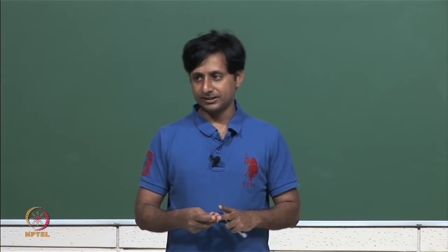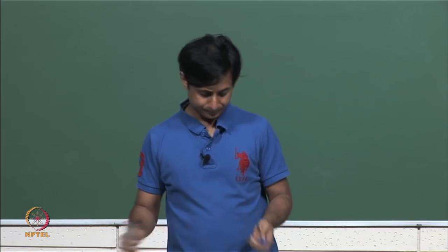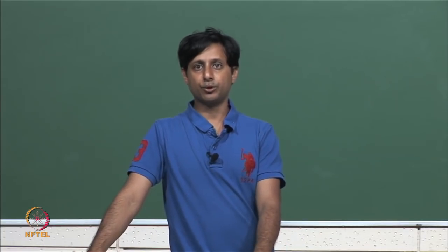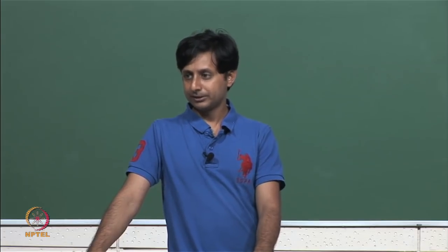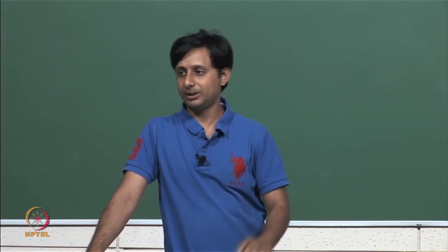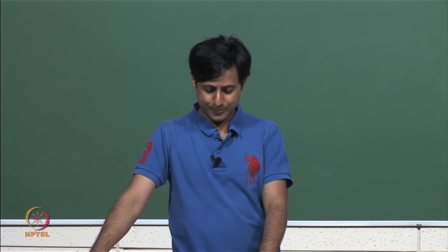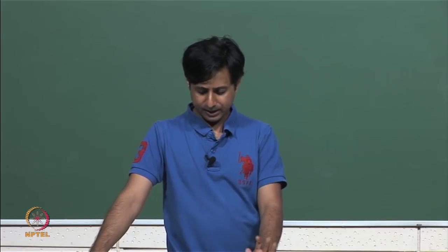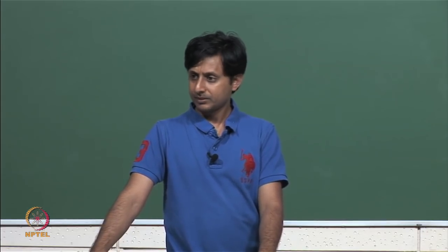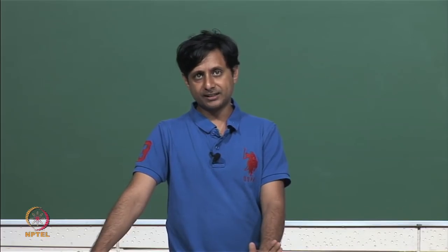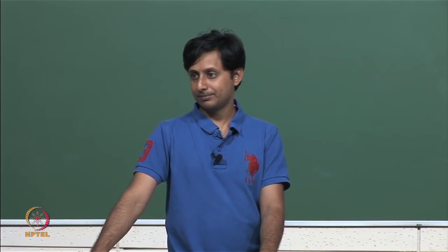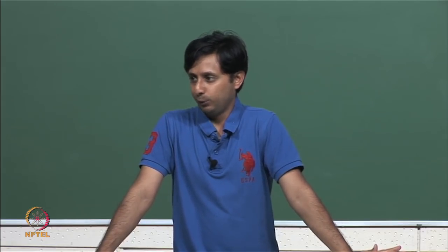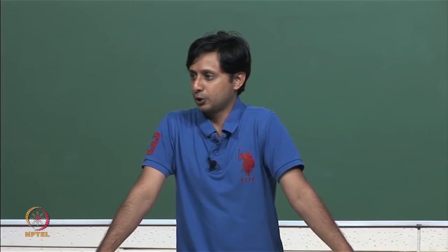We will also learn how to tackle the zeros a little later. Okay. Sometimes the right half plane zeros are going to pose as problems, right. So, we are going to learn how to tackle them separately, that is a separate exercise. For now, forget about the zeros. Now, in this situation, we have to make sure that the ratio of the two poles is the set number that we had arrived at before based on the Boss's specifications.